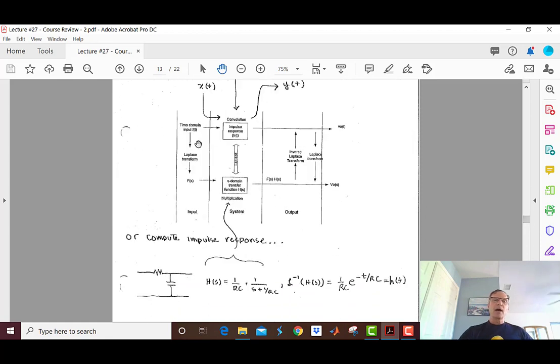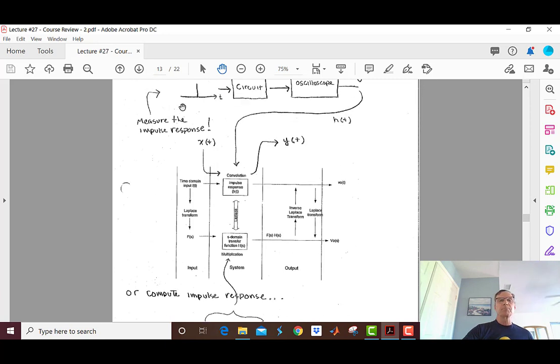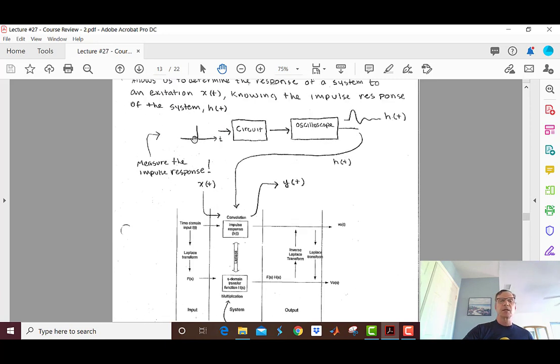So here's my filter and my impulse response. If I put an impulse in to the input, instead of getting this little boingy here, I'm actually going to get a up, hold for a bit, down. See that? My impulse response, or what the output does when I put an impulse in, is up, down. That's the impulse response of this rascal.